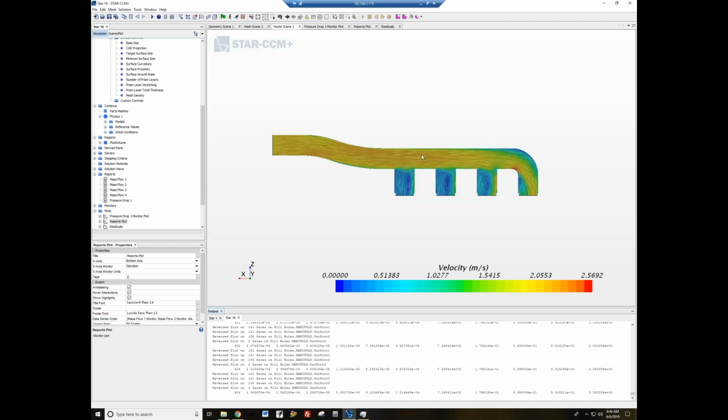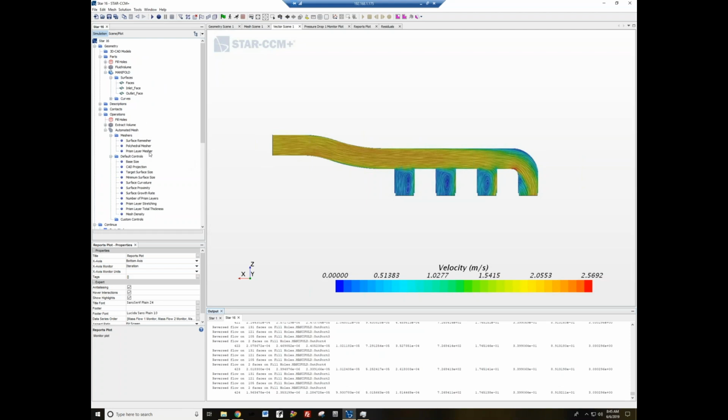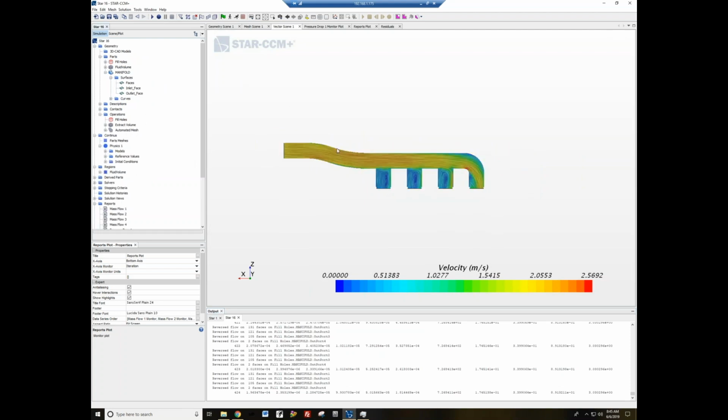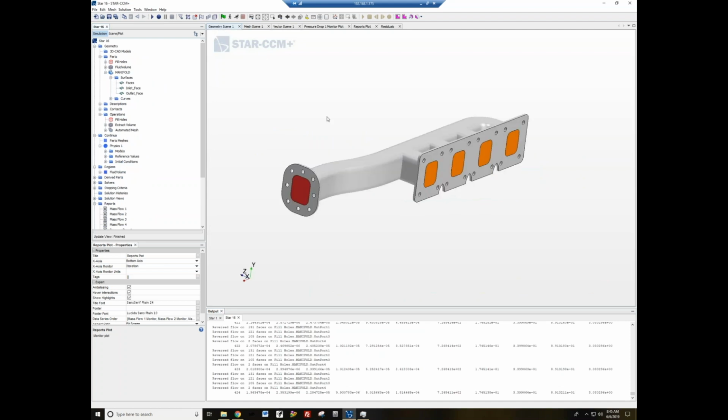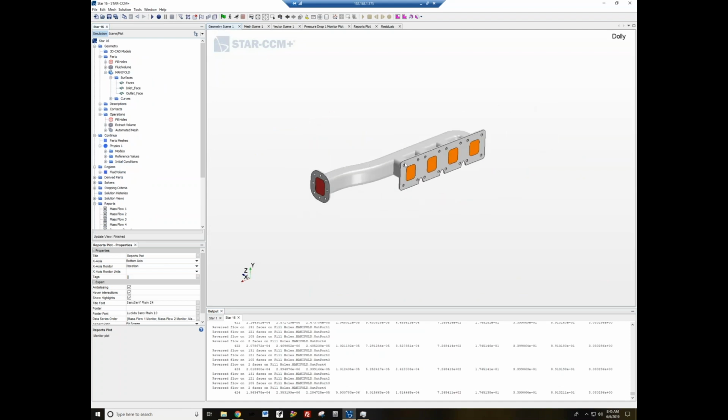Typically, it's good analysis practice in CFD to make sure that the boundaries you're applying are situated some nominal distance off the part that you have an interest in. So typically you don't want to be forcing boundaries like this, and it's a pretty easy correction to make in STAR-CCM+, so that we can address this concern by extending these boundaries out.